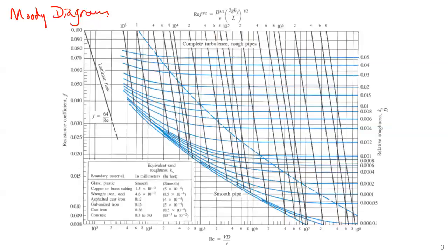And again, the Moody diagram can be described by equations. So you had a handout with this Moody diagram. And on the other side of the handout were all the equations that describe different parts of the diagram. Most of those equations and the Moody diagram are in your textbook. Remember, there are basically 4 axes on this plot. One is the friction factor on the left-hand side. The lower horizontal axis is Reynolds number.